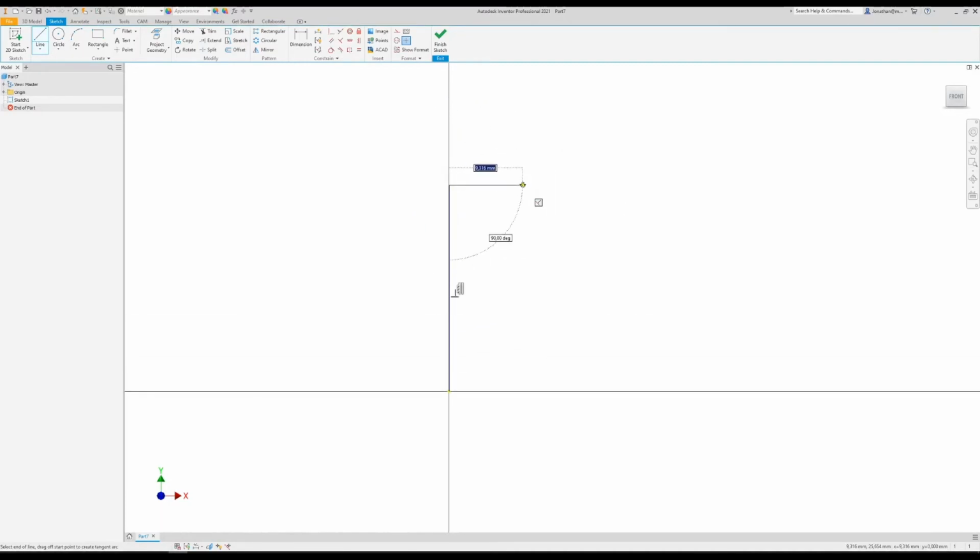And when I go to the right, I want the rest of the shape that I draw to not be constrained. And what you do is you just press Control on your keyboard. You'll see there, when I'm not pressing Control anymore, it's snapping perpendicular. I'm going to press Control, move my mouse up, and you'll see that now I actually can't get it to snap. So I'm just going to keep holding Control, and I'm just going to eyeball the shape.